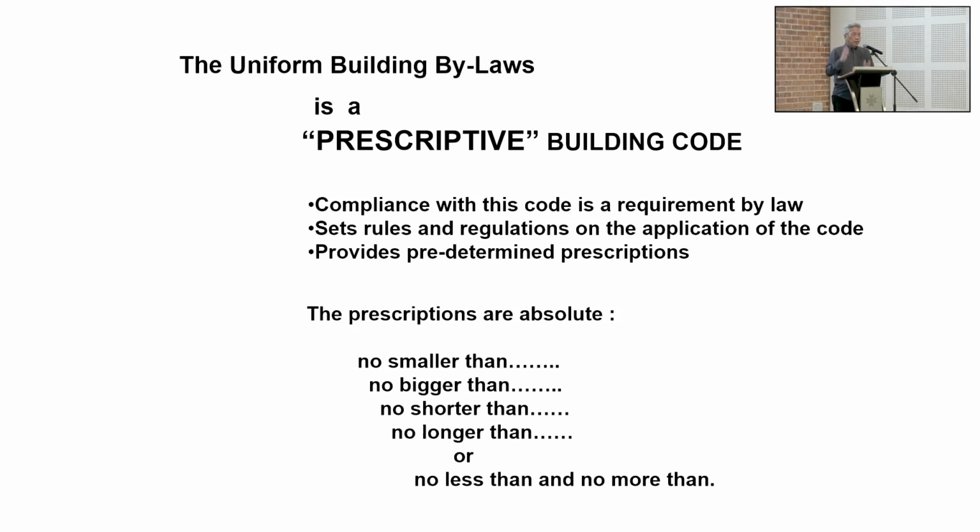So we figured at that time, or rather Bomba, particularly Bomba, figured that our Uniform Building Bylaws, 1984, could not cope with developments like the KLCC. You cannot cope with developments like the KLIA. Because if you look at just our compartment limits, limits of compartment for fire zones, 7,000 cubic meters. What is the volume of the KLIA? Just one small hall is already exceeding that. So we find that a lot of things we cannot cope with.